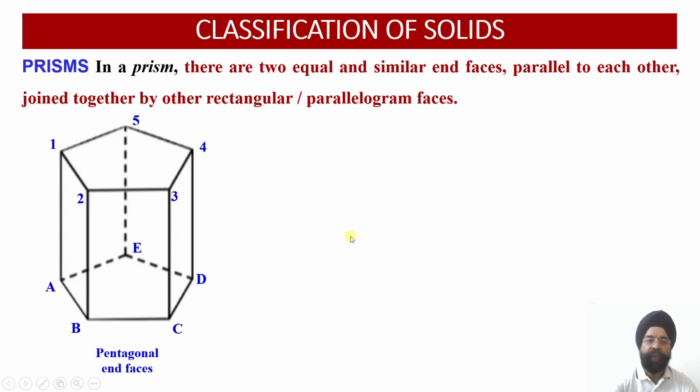And again, one thing we must remember, whichever way this solid will be oriented with respect to HP or VP, we must join A, B, C, D, E under all situations. We must be able to join 1, 2, 3, 4, 5 because this represents a surface under every circumstance. Then we must also join A1, B2, C3, D4 and E5. And we must also join the axis line using the axis representation.